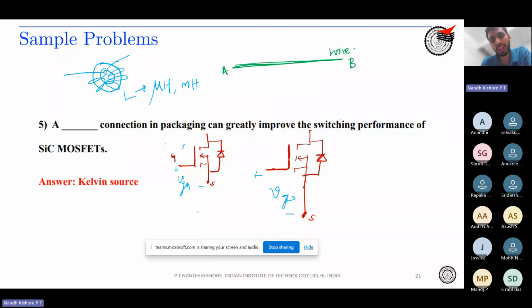But the wire will intrinsically have some resistance. It is just copper wire, but still it will have some resistance, and it will have some inductance. This inductance comes about due to the physical dimensions of the wire. As the wire length increases, both R and L also increase as the distance increases.